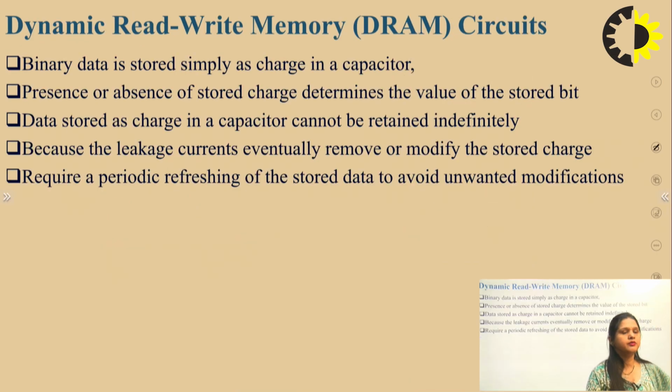Now come to the important topic, which is the dynamic read-write memory, or DRAM cell or DRAM circuit. The concept is to store the data as a charge in a capacitor. Presence of charge is considered as logic 1, that is high level, and absence of charge determines logic 0.